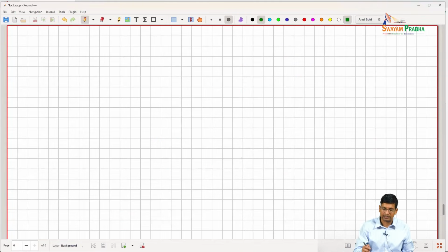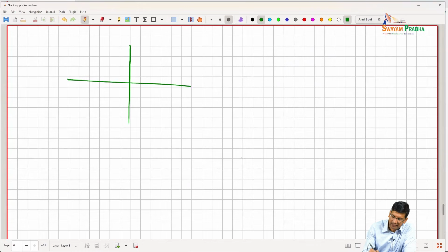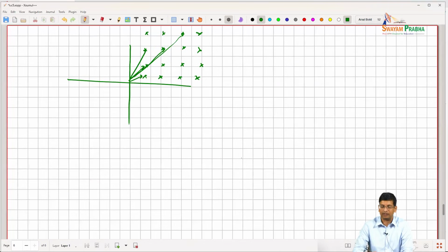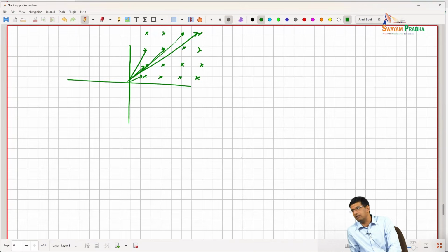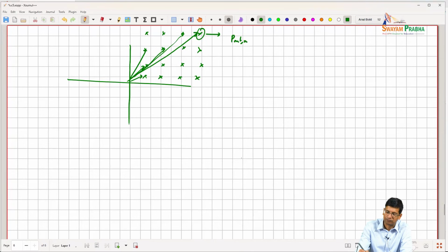The second phenomenon is that in this kind of quadrature amplitude modulation, if I have constellation points, and again I'm only drawing one quadrant here, you can see that the amplitudes of all these vectors are different. So I might have a peak that is here, and then the average will be the average of all the constellation points that I have. So when I'm designing my PA, this basically becomes the P out max of my PA.